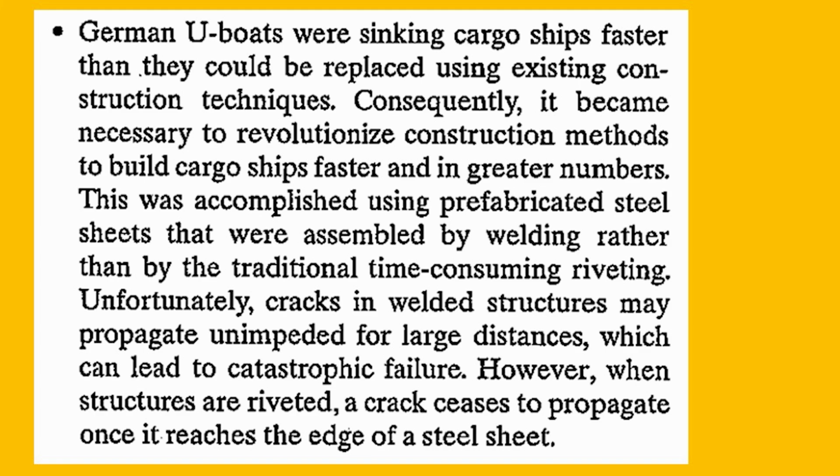And unfortunately, cracks in the welded structure may propagate over a large distance, which can lead to catastrophic failure. However, when the structure is riveted, the crack stops propagating once it reaches the edge of the steel sheet.